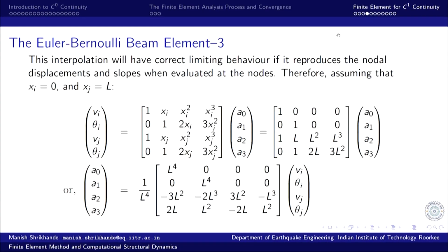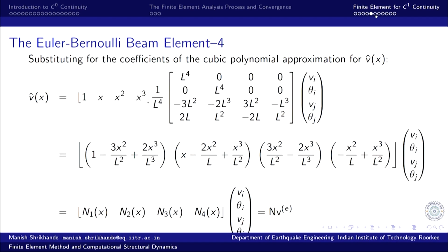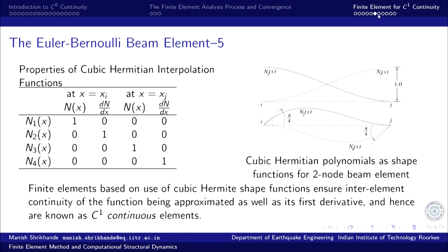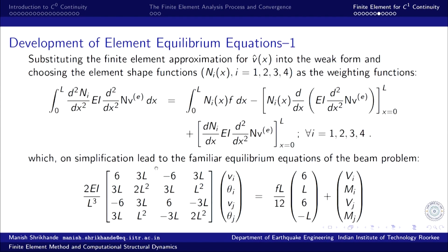So, in this particular stiffness matrix that we computed for the Euler-Bernoulli beam element, we will have 2 more rows and columns corresponding to ui and uj, and the respective elements would be decoupled from these flexural degrees of freedom, and there would be appropriate AE by L, AE by L, minus AE by L off diagonal terms in the respective row and column positions of this stiffness matrix.